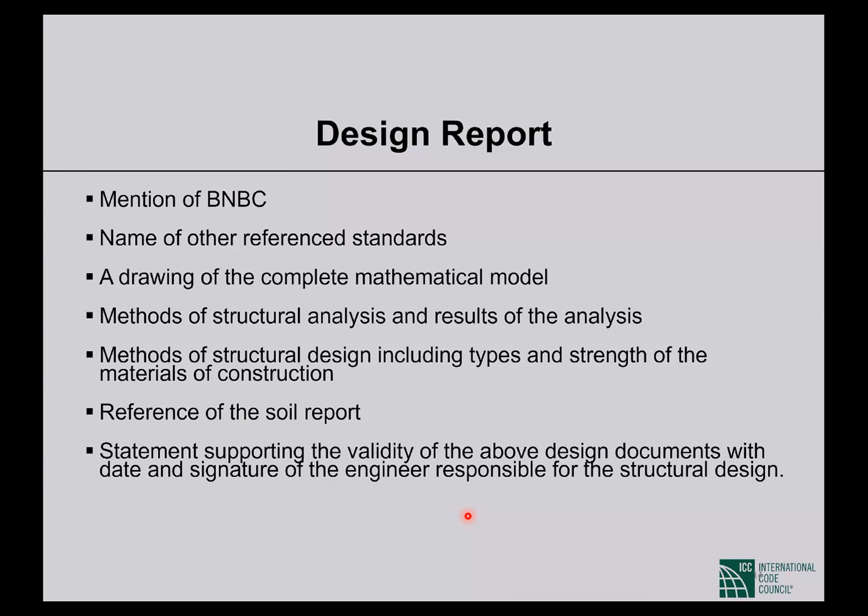If we do that, then in the drawing of the mathematical model, the brick walls should be shown as struts instead of walls. So that is the mathematical model. Methods of structural analysis and results of the analysis. There are different methods of structural analysis. We'll see, for example, to consider earthquake loading, what are the different methods of analysis. So which method of analysis is followed should be mentioned, and results of the analysis.